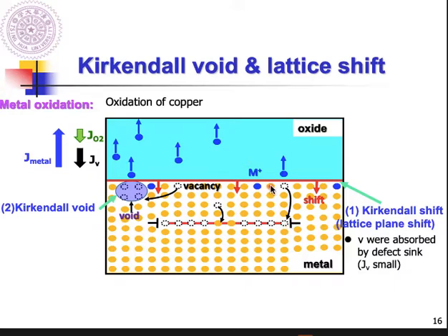As long as the vacancy replaces all the atoms in this dislocation, the dislocation is going to disappear. So that will allow this plane interface or lattice plane to shift toward the metal side. In this situation, you will observe the plane shift.